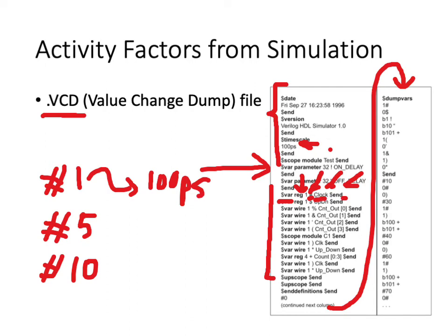The reason there is a symbol per register is because the .vcd tries to save the information in a compressed format. It does not record the full name of the net, but rather uses a symbol to represent the net, typically a 1 byte ASCII symbol.